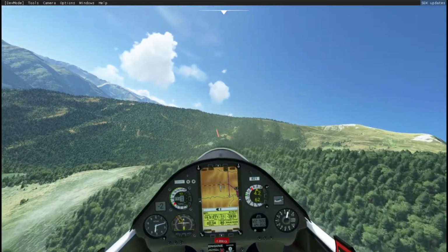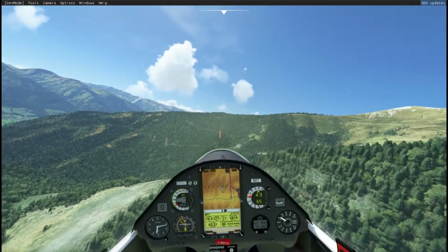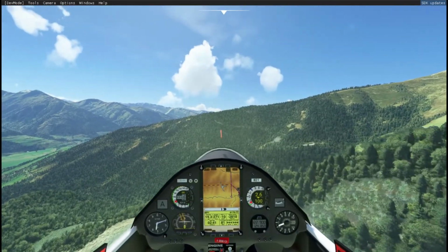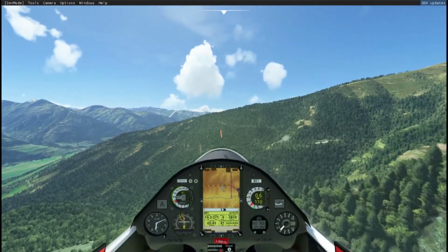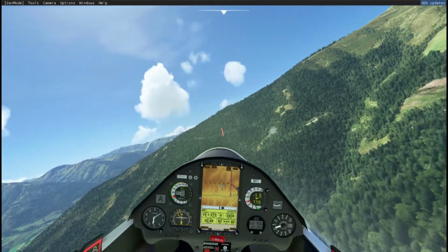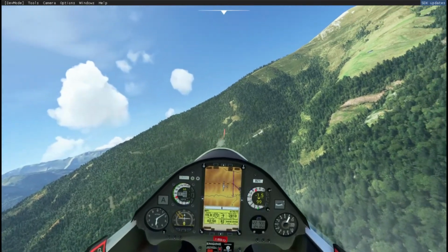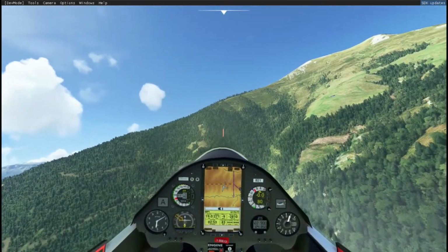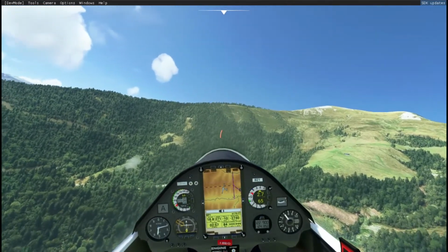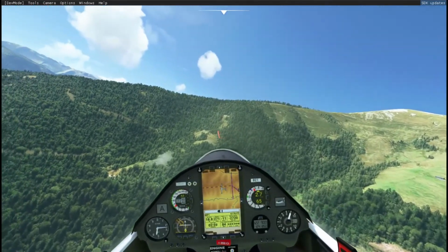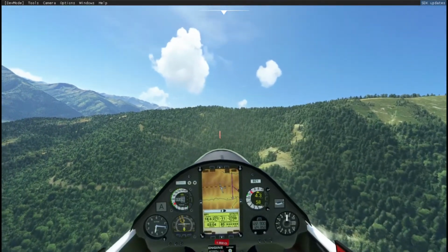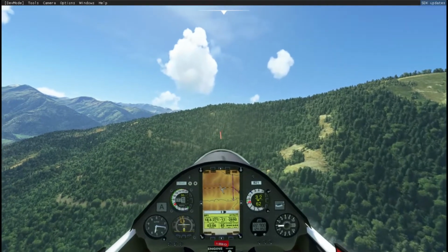So -2 is too negative a flap setting for the speed we're flying. You wouldn't be using -2 until you're doing, say, 90 knots. Then it would be the most efficient flap setting for that speed. Below 90 knots, down to, I don't know what, 80 knots, 75 knots, you'd be in -1. Below that, you'd be in 0. And then for normal, just straight flying, you wouldn't go below 0. In fact, it probably wouldn't go below -1. You know, -2, -1, 0 for straight ahead flying.